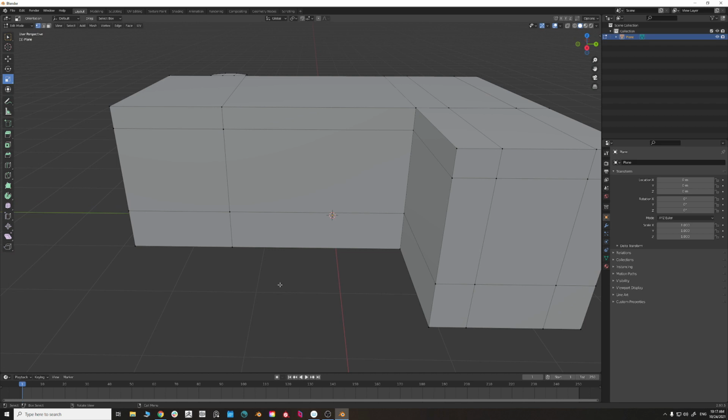And let's create the windows that we initially wanted. So I'm going to go to edges. I'm going to press Control and R, or select it from here, to use the loop cut. And I'm going to create a bunch of these windows. Like I'm going to do 2 here so we can have the window. And I'm going to do 1 here. Again,